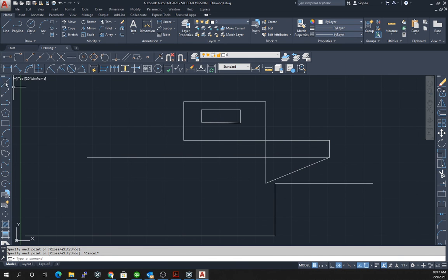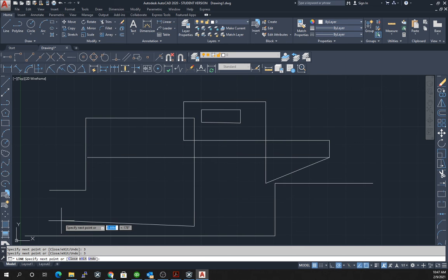So that pretty much covers everything that we went over last week, all of the individual details. Oh, and the final one, which is very easy. Once you're using the polar tracking, you don't need to type both the X and the Y dimensions. So when you're moving, let's say in the X dimension, once I have a line going in this dimension, if I want to make a line an inch long, all I have to do is type 1 and hit enter. And that does it. If I'm moving vertically, I want a line of length 2, I can just type a 2 and hit enter. And I make a line of length 2. If I want to make a line of length 3 here, I type a 3 and then enter. And that makes a line of length 3. And I'm not sure why that line of length 1 looks so short, but I want to come down by 3, type a 3, and then go back by 4, and then up by 1, and we complete that box. So you don't always have to type both the X and the Y dimensions.